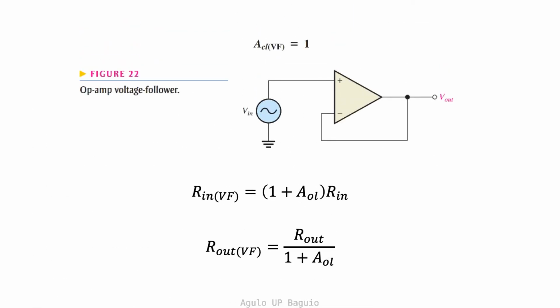The simplest type of op-amp circuit is the voltage follower. The feedback is just a straight connection between the output and the inverting input. According to golden rule number 2, the inverting and non-inverting inputs should be equal. Thus, the output voltage is equal to the input voltage and the voltage gain is unity.